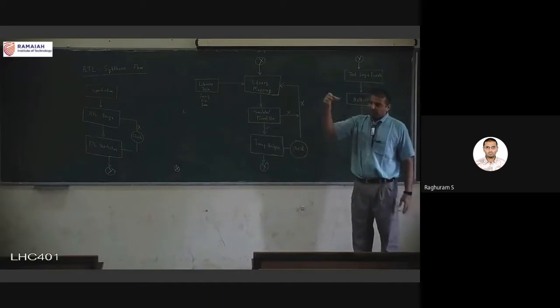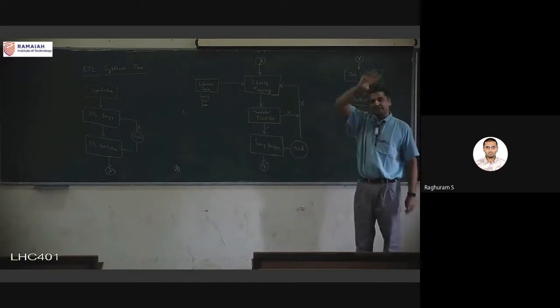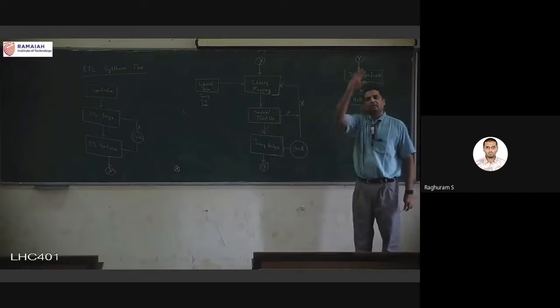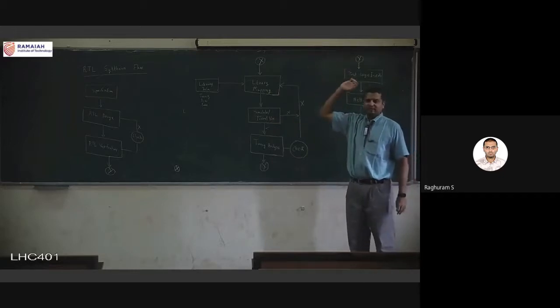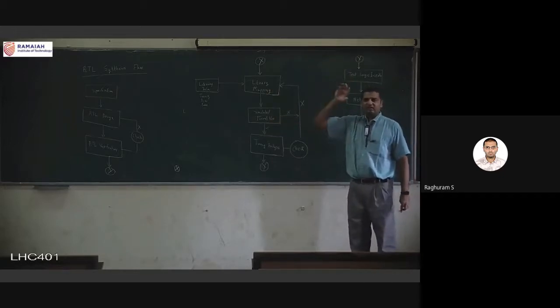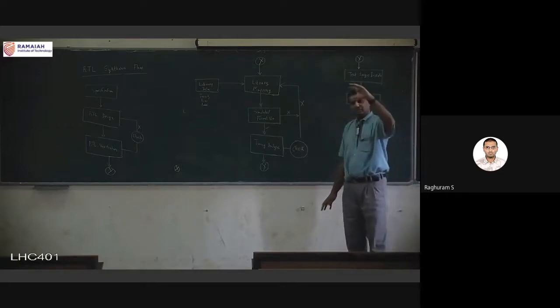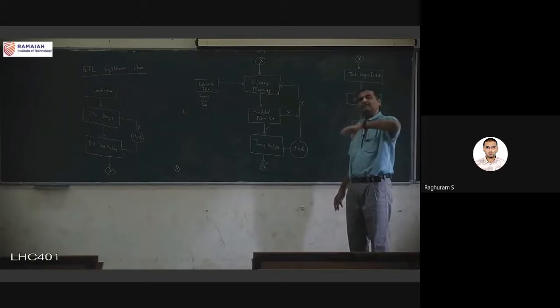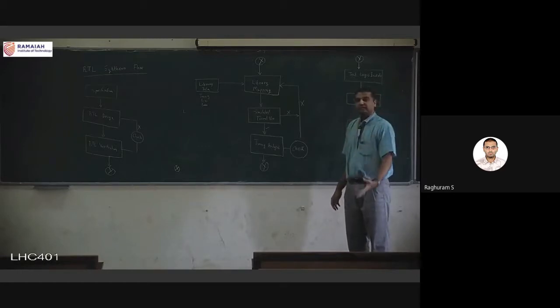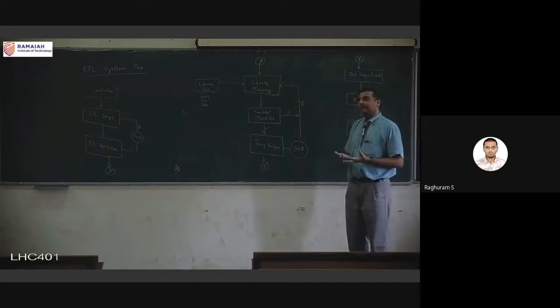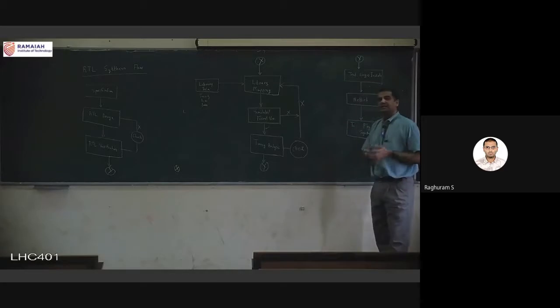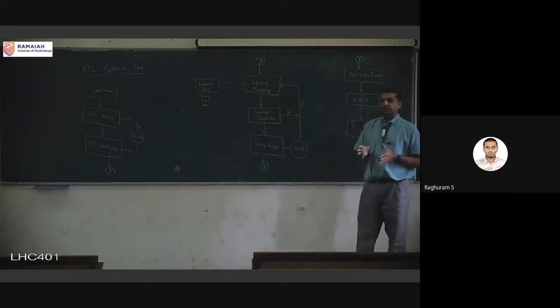You keep your IC inside that, and it has a lot of complicated signal generators, a lot of analog signal generators, a lot of digital pattern generators, and a lot of hardware circuitry by itself. And it will test that circuit by putting it in test mode, and that might take a few days by itself. Okay, and once all that is done, then you know that finally the fabrication errors are also not there.